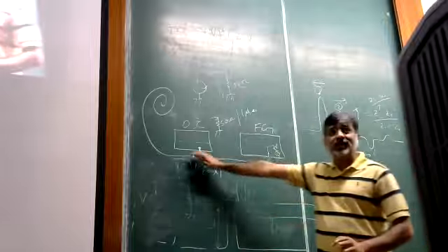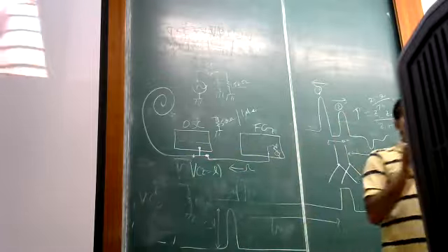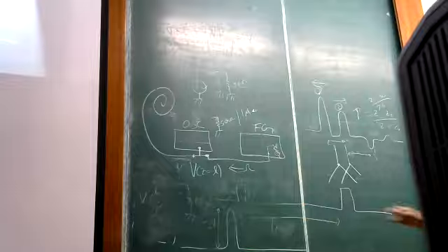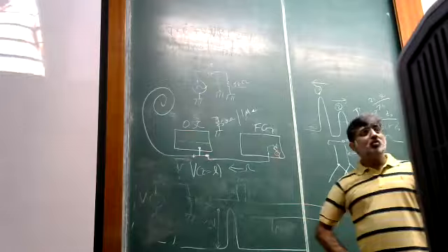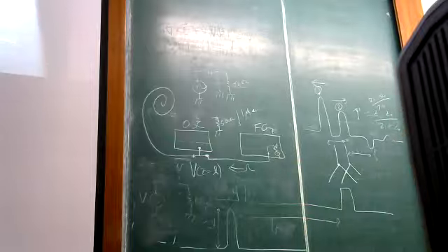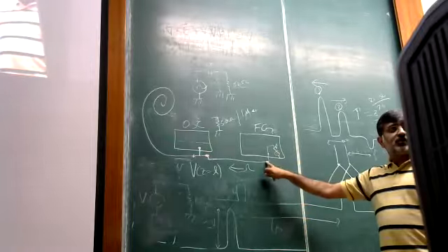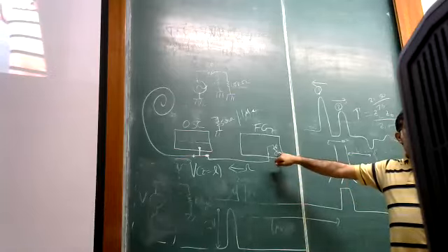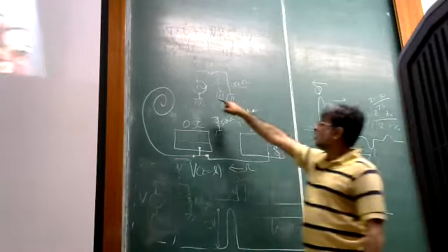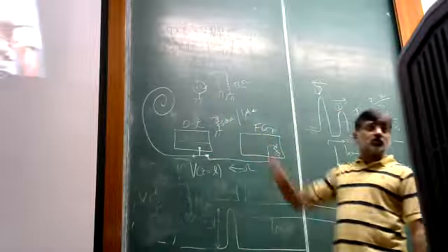It has no idea what is coming, because this is all local in time. So when the pulse is launched, it's launched from a 50 ohm source to a 50 ohm load. So the amplitude of the wave here, the height, is going to be V/2, where V is the original source voltage.